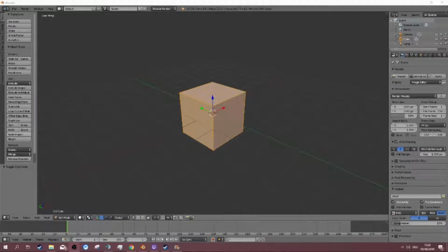So now, when you're exporting into your slicing software, you have to keep in mind that the slicing software can't handle not closed objects. If you have a hole in your object and you try to print it, then you will get ugly lines inside, like lines are missing, or it won't render it properly, or it will leave it open, or shit happens. So you always have to close something.